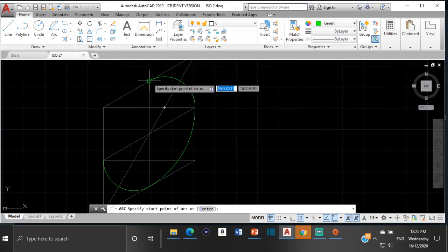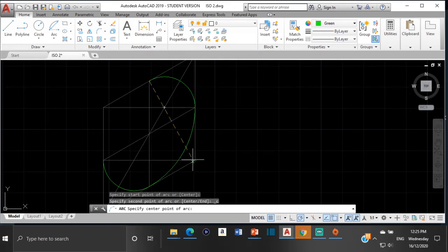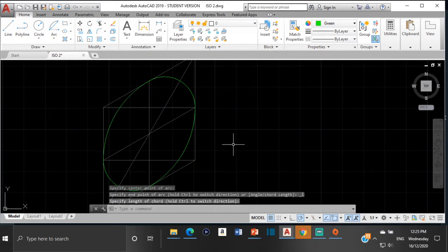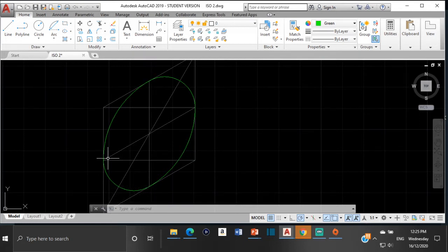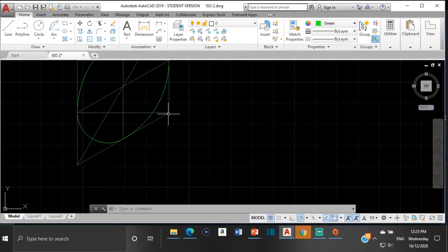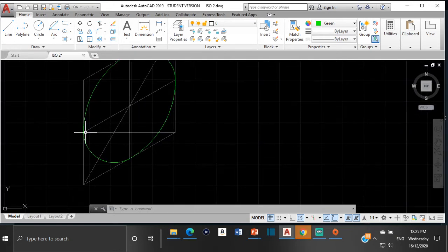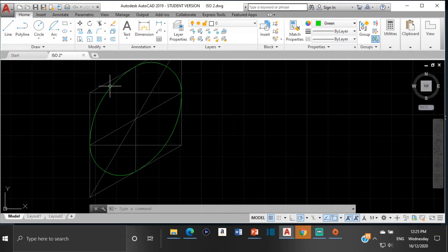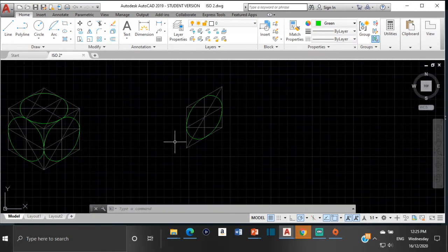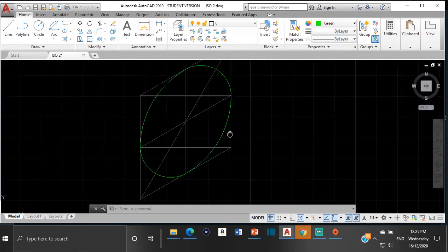This time, let's see if we start here, use this as the center, and then this is the length right there. Okay, so again, start, center is here, then it ends right there, and we finish our isometric circle right there. And if you were doing this on paper, compass point right here, open your compass to this point here, and then you scribe your arc, and you get that. So just like that, we have this isometric circle here. We just reproduced it over.